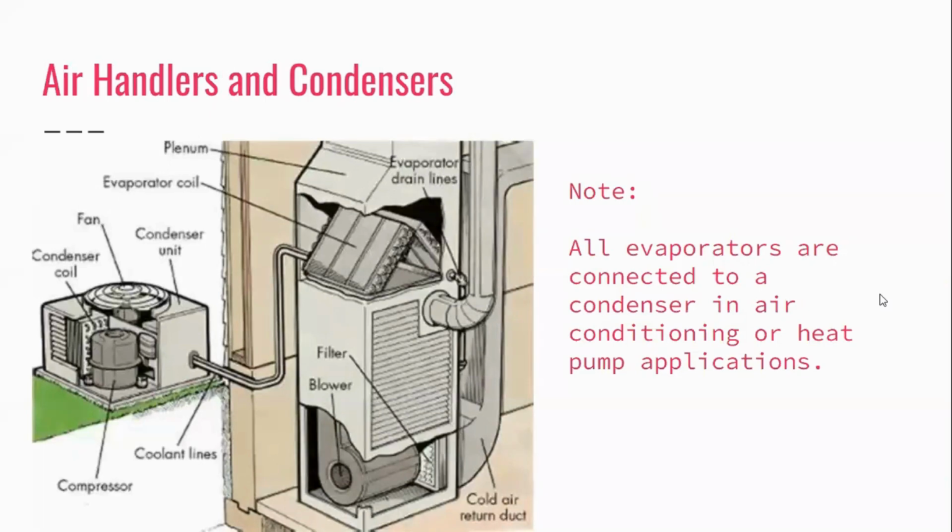Self-explanatory again, guys. This is an air handler. So this is just to show you guys that setup I was talking about where you'll have a furnace and then you'll have an A coil on top. It all is within the ductwork. It will look like one system. You've probably seen a million of these in your life. You just didn't realize that they were two separate systems. They're not. They work as one system, but it is technically two separate components.